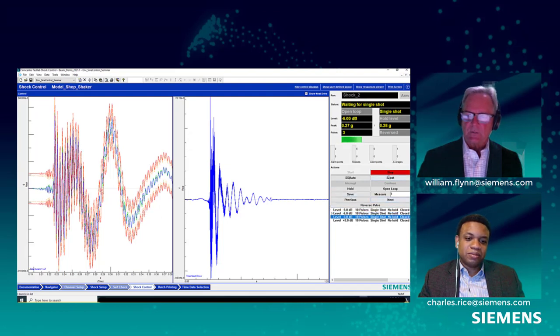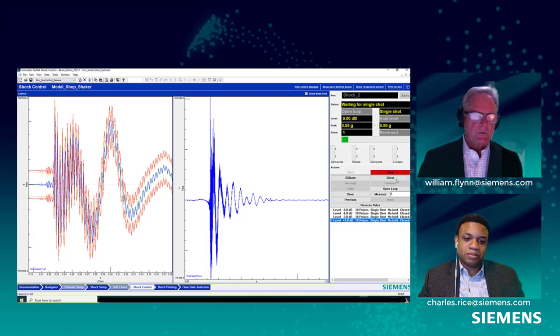If I go to the next one, I'll shoot. It's a bit closer. It's got a good estimation of the transfer function, and shoot again. And it's even closer after an updated transfer function. Let's go to our final level, full level, shoot. You can see it's some nonlinear response, very minor, but we go again, and now we'll update the transfer function with the next one, and we should be closer to the reference, which we are.